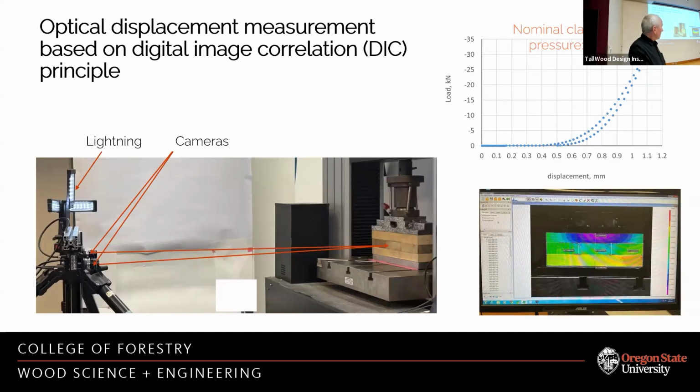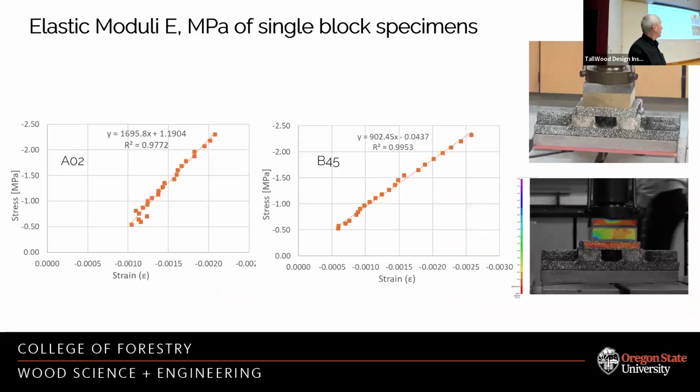If there is deformation in the central block, it means the load has actually been transferred. If there is not, there is no load transfer. And then we do it in gradation, how much of the pressure is actually being transferred. Before we can do this intelligently, we are talking about strains. Only those can be measured. Stresses cannot be measured. You can calculate stresses if you know the elastic moduli.